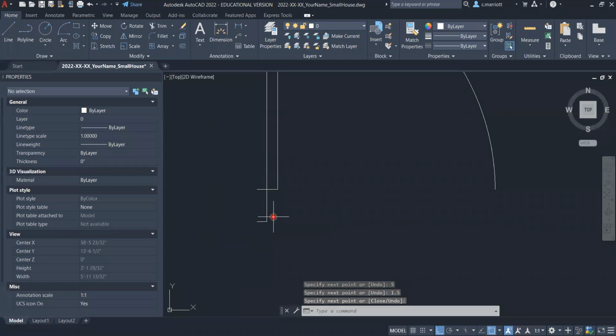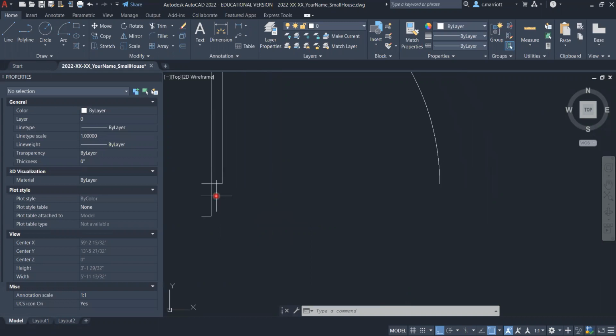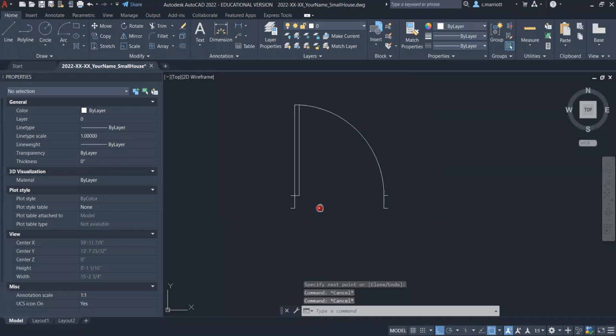Right, so this is the door frame. The wall will come along here and then turn, or whatever that particular condition might be. I'm going to repeat these lines over on the right side. Line from endpoint, 1.5, line from this endpoint down 5, and to the right 1.5. Right, so these are all of the components necessary for my block.